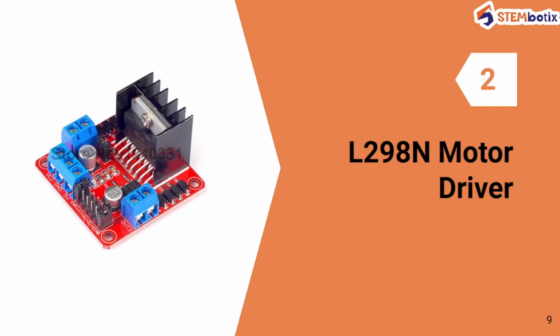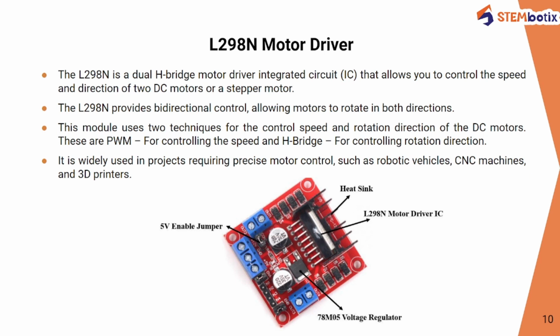Now let us see the particular L298N motor driver. As we discussed in the beginning of the video, the L298N motor driver is very crucial, and when you add this motor driver, the control of a particular motor is made easy. The L298N motor driver is a dual H bridge motor driver integrated circuit that allows you to control the speed and the direction of two DC motors and a stepper motor.